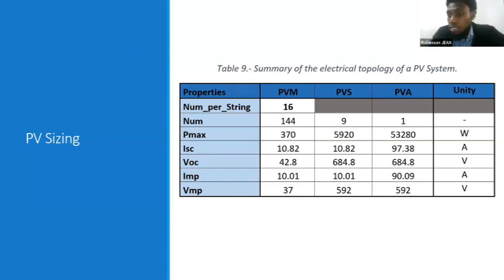Some people do this with one panel, two panels, for instance. And one day, if the available power is for 5 hours, so in 5 hours with a panel of 300 watts, you will have 300 watts times 5 hours, so it will give you like 1,500 watt hours.